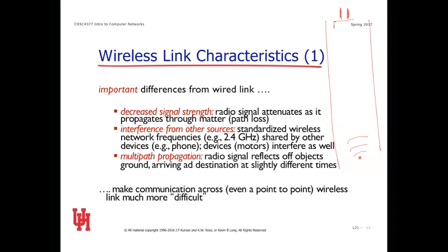And we've already talked about how what you're really sending is this ever-increasing sphere of energy. And every millimeter greater radius for this sphere, the greater the surface area of the sphere. And the energy that you've imparted to transmit the signal gets weaker per square millimeter on the surface of the sphere because the same amount of energy has to cover a sphere that's getting bigger and bigger. And so, of course, if the sphere has the same total amount of energy, even if you ignore signal degradation from distance, there's less of it just from the surface area equation.